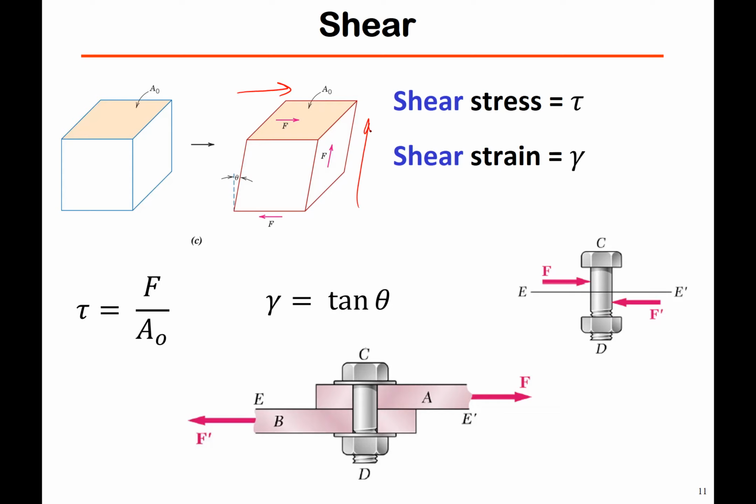Instead of sigma and epsilon, you may have already seen this, where it's actually tau and gamma. Now, this is not to be confused with tau, the relaxation time of a polymer after we've applied a stress in for very particular cases. So we'll go over the properties of viscoelastic polymers where there's also a tau involved. So clearly you must take it within context what the tau actually represents.